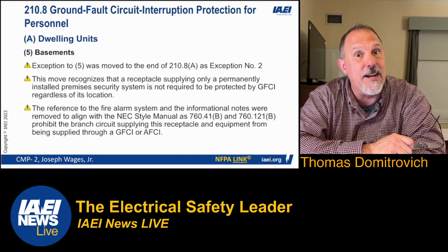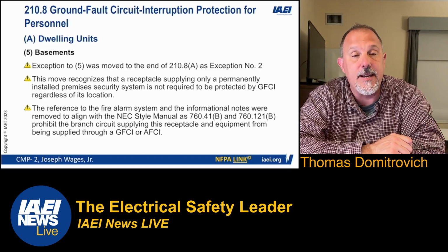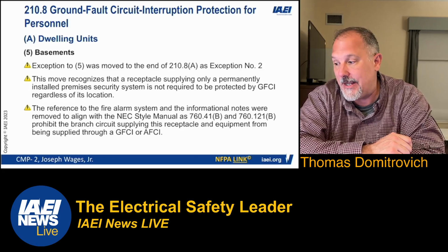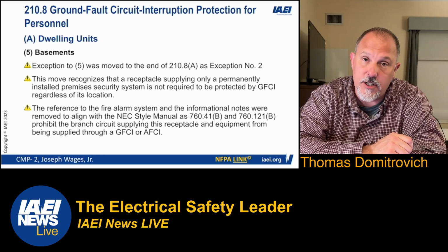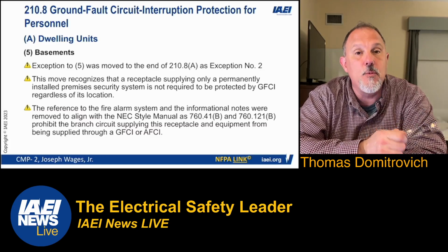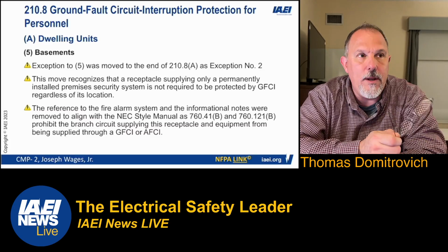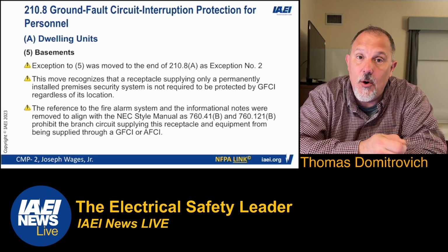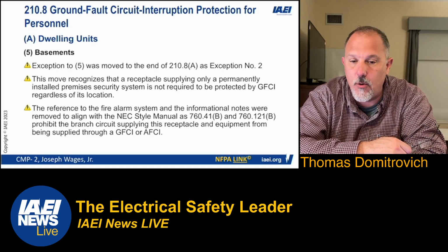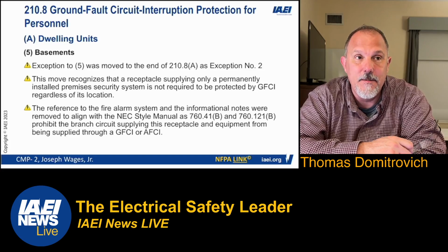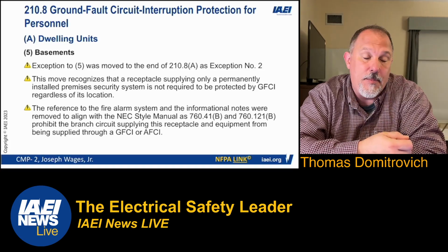Remember, chapters 1 through 4 apply generally. Chapters 1 through 7 can modify or amend chapters 1 through 7. So if I say in 760 that you shall not put this on a GFCI, then I don't care what room it's in. Think about this. This exception was only to basements. We have requirements for garages for GFCIs. We have requirements for laundries for GFCIs. What happens if I put my security system or my fire alarm system in my laundry or my garage? I would be in conflict.